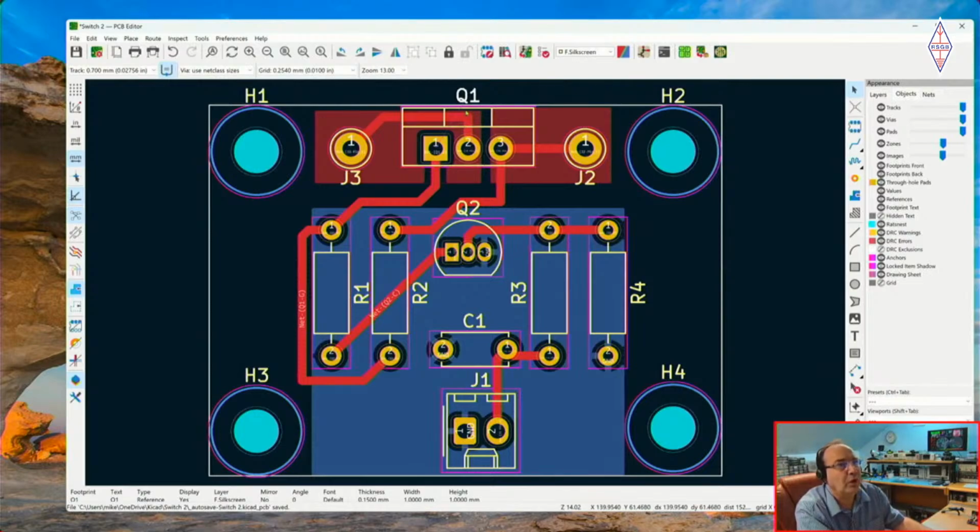So I'm going to move this Q1, which is currently off the PCB, and I'm going to put it, say, here. I'm going to move, well, R1, C1, they're okay. R3 though, it's a long way up, so I'm going to rotate it. I'm going to put it on top of the resistor here. Shall I put it on the top or the bottom? No, let's put it on the bottom. I'm going to put it here. R4, R2, R1.